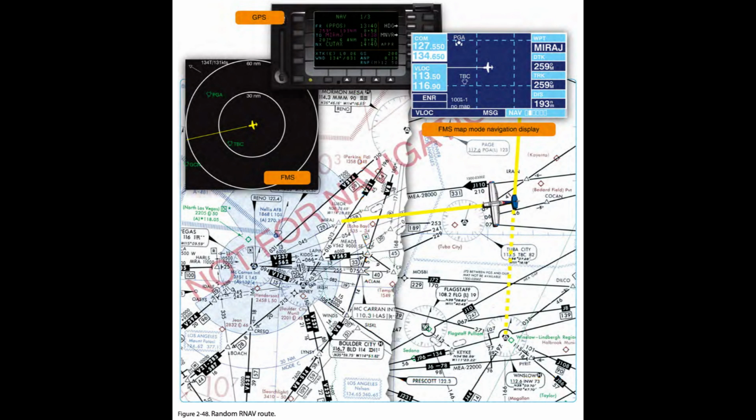FAA facilities, such as automated flight service stations, AFSSs, and ARTCC/sectors, are usually the control point for NAVAID facility status. Pilots can query the appropriate FAA facility if they have questions in flight regarding NAVAID status, in addition to checking NOTAMs prior to flight, since NAVAIDs and associated monitoring equipment are continuously changing.